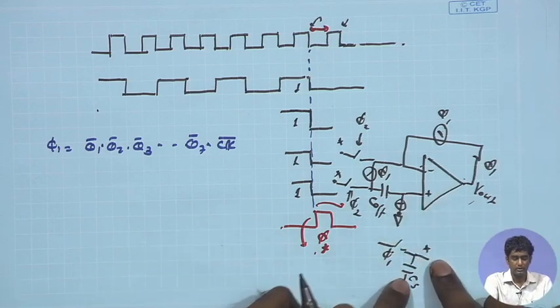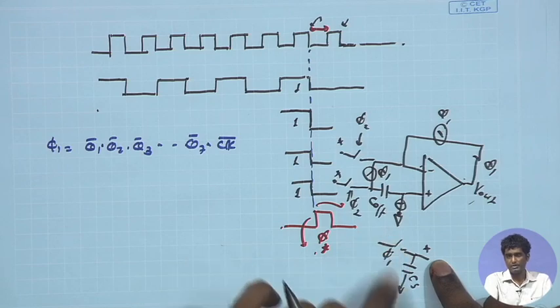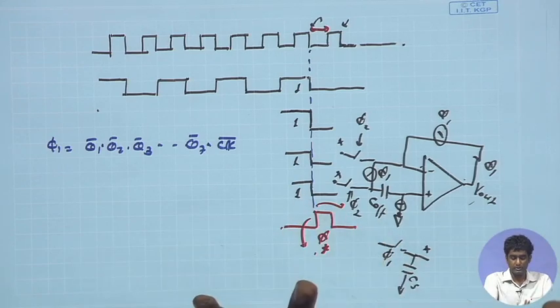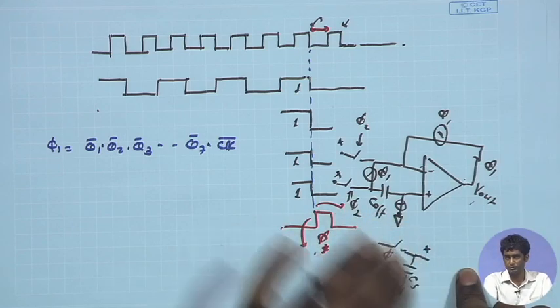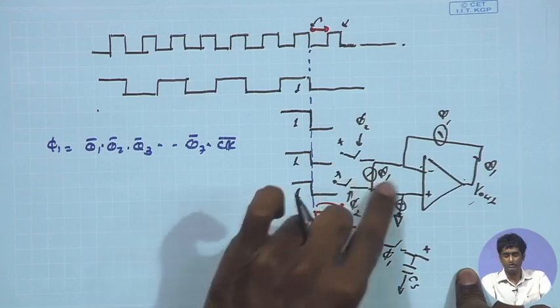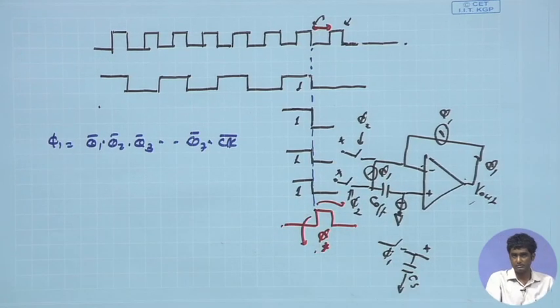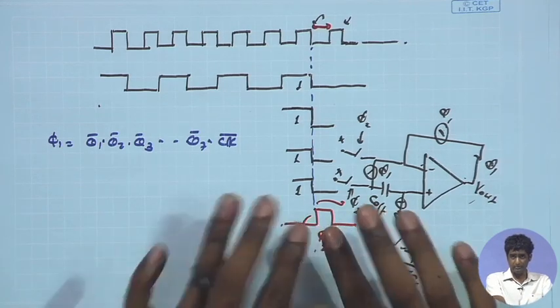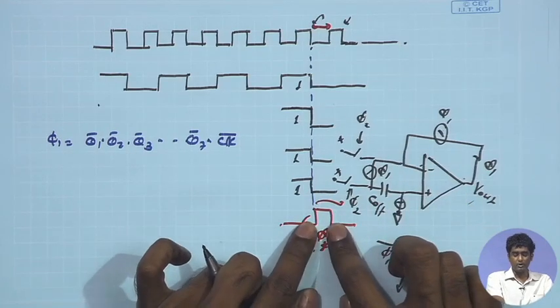If you just, for instance, increase the size of the switch a little bit, and corresponding to that, just to preserve the same voltage level and signal integrity, you increase the Cs, so that leakage is not causing the droop. So, this is also relatively straightforward, but the constraint comes here. So, for that we can discuss another extension where you can try to make this phi 1 programmable, or you can have a longer duration for phi 1.